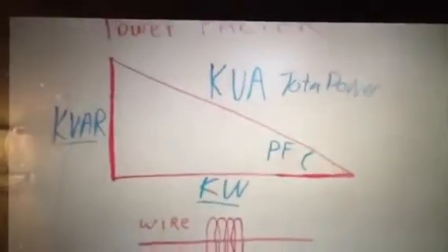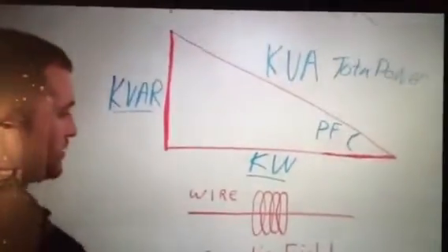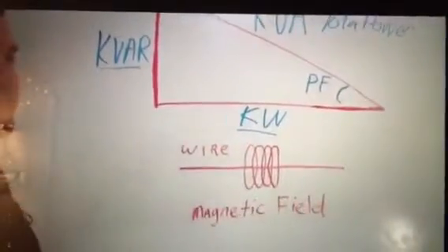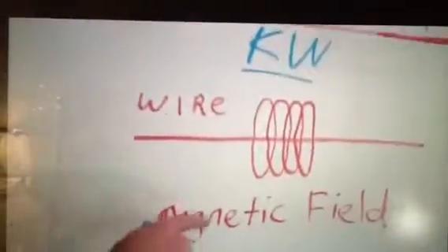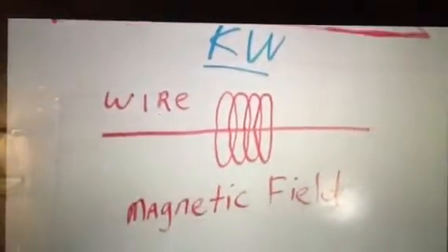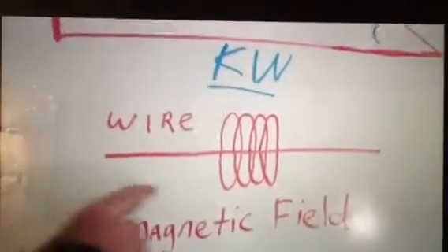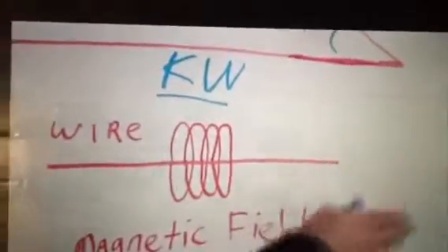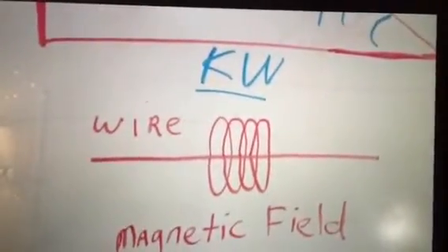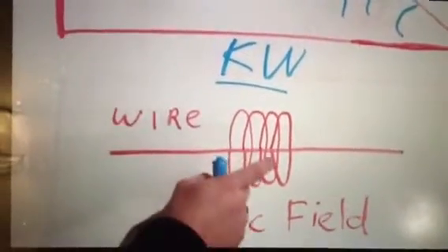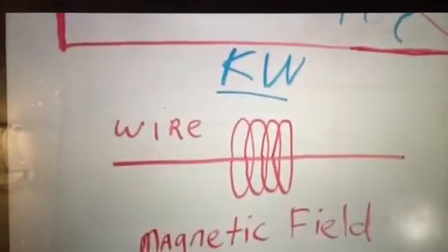Now to help me further explain power factor and reactive energy, we have a little drawing down here, and what this represents is a piece of wire, maybe in an electrical industrial facility, and this wire, you can see these rings around, that represents magnetic fields. Before current will flow down this conductor to a motor or some other electrical device, magnetic fields have to be developed around all those current carrying conductors. Currently, this real energy is being provided by the electrical utility. And now I'd like to show you in a live demonstration how this works.